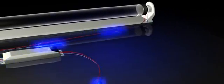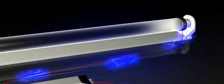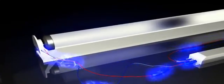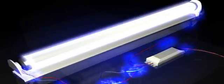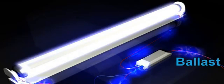The sealed glass tube is coated with a thin layer of phosphorus and contains a small amount of mercury and an inert gas, such as argon, under very low pressure. There are electrodes at both ends of the tube. When high voltage is applied to the electrodes, an arc passes between them, ionizing the mercury in the tube and producing ultraviolet energy, which in turn excites the phosphorus and transforms the UV to visible light. All fluorescent lamps require a ballast to control the flow of current to the lamp. This aids in starting the lamp and in continued operation.